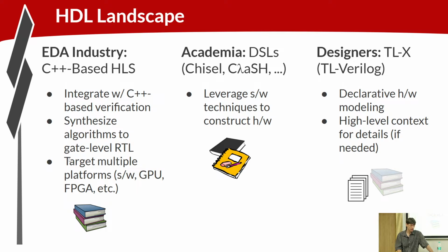It's a nice ideal. Generally, this works out well for software teams that are working with C++ designs, and that's their starting point. How do you get from that starting point in C++ to a hardware implementation? High-level synthesis is a tool that can help with that. Generally, though, you may be a bit naive going into it, thinking I just take my C++ code, I push a button, out comes a hardware model, and my algorithm runs faster. Generally, by the end of it, you've become a hardware engineer, and you're essentially writing RTL using C++.